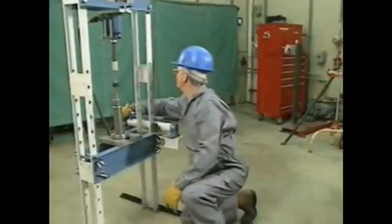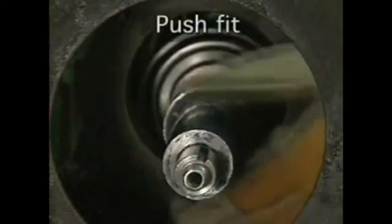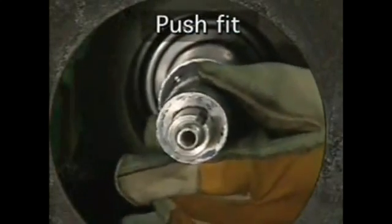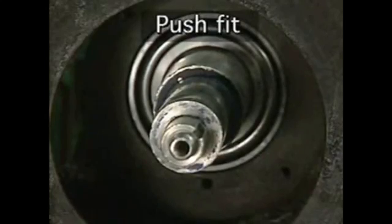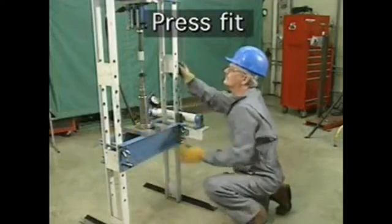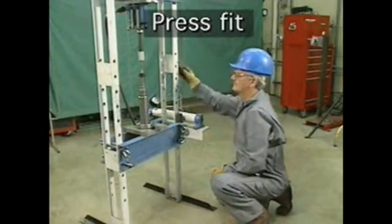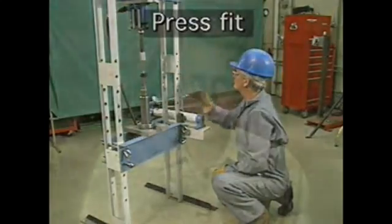There are two kinds of fit: push fit and press fit. A push fit is a fairly loose fit. Usually a ring that has a push fit can be pushed into place by hand. A press fit is much tighter. More effort is needed to press the ring into place. A press fit is also called an interference fit or a shrink fit.